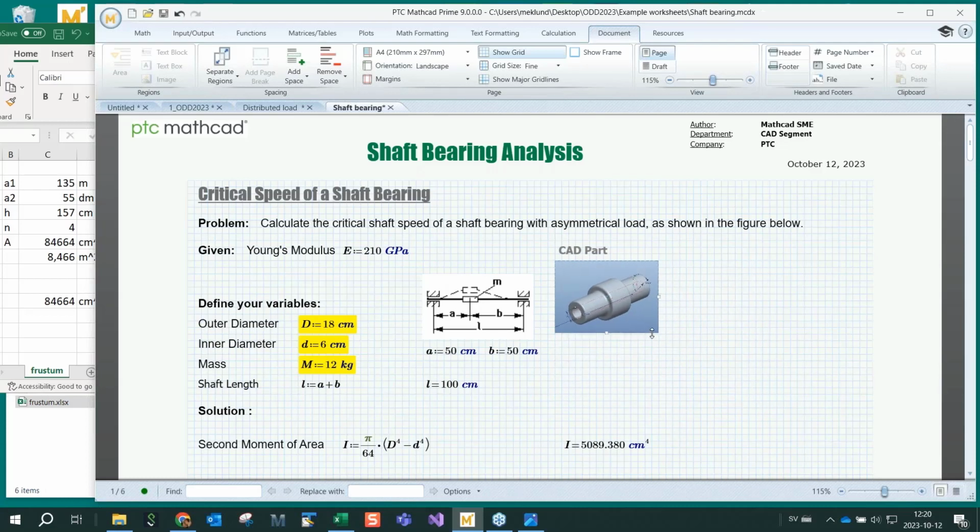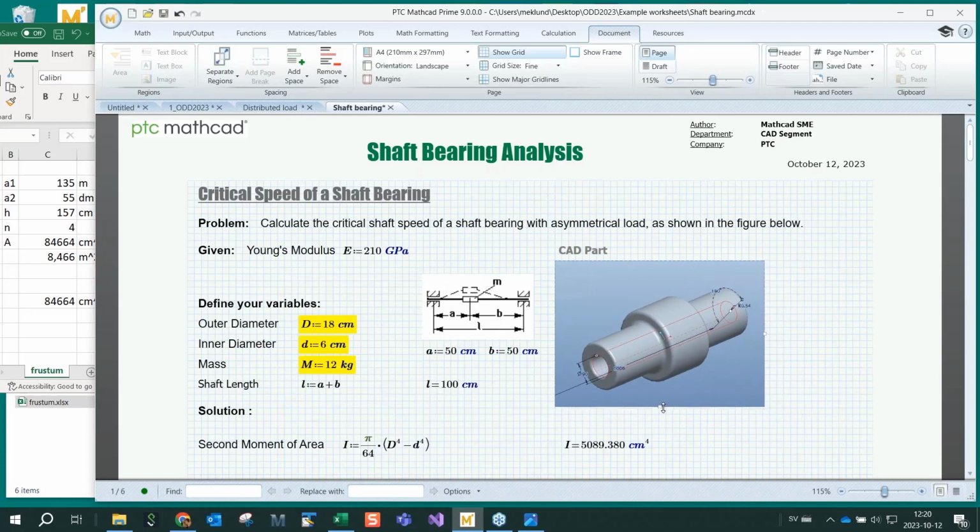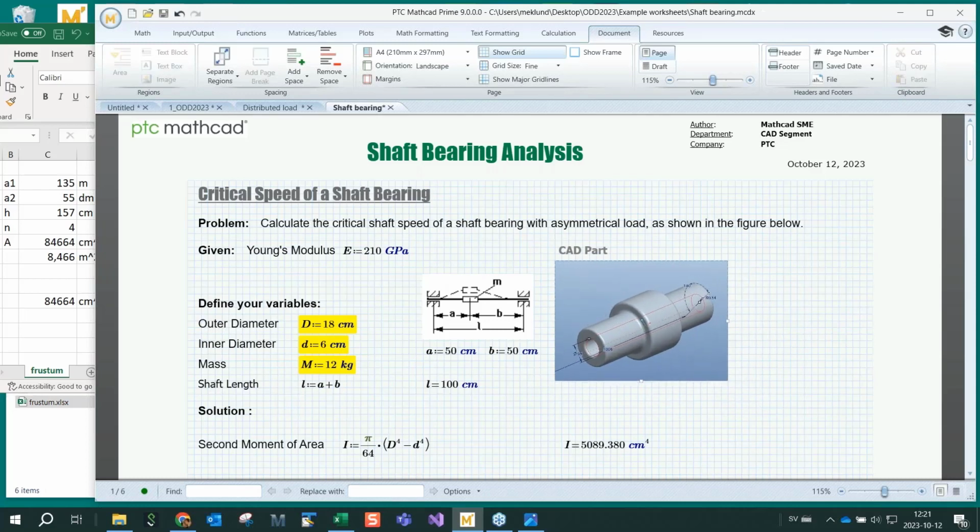So making them smaller, and as I see it, it's often better to change the size in the drawing software and copy paste it in at 100% and not change the size inside of Mathcad. That often looks best. There's no feature in Mathcad other than just doing this. Okay, thank you.